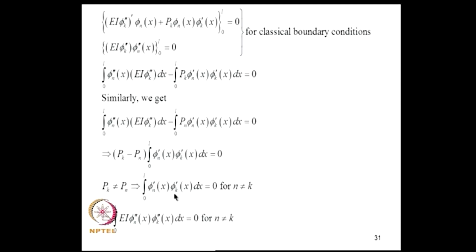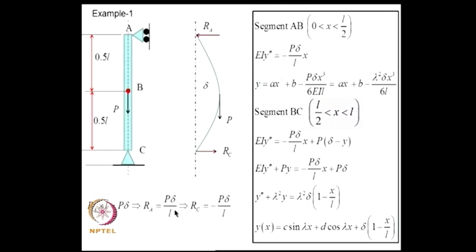So, if you recall in vibration problems, the mode shapes that we obtained were orthogonal with respect to m and EI. Here again we get similar orthogonality relations. Now, what I will do now is I will consider a series of 4 or 5 problems again aimed at gaining familiarity with how to deal with problems of stability analysis. Many of these problems can serve as benchmarks when we develop the finite element method to handle these problems.